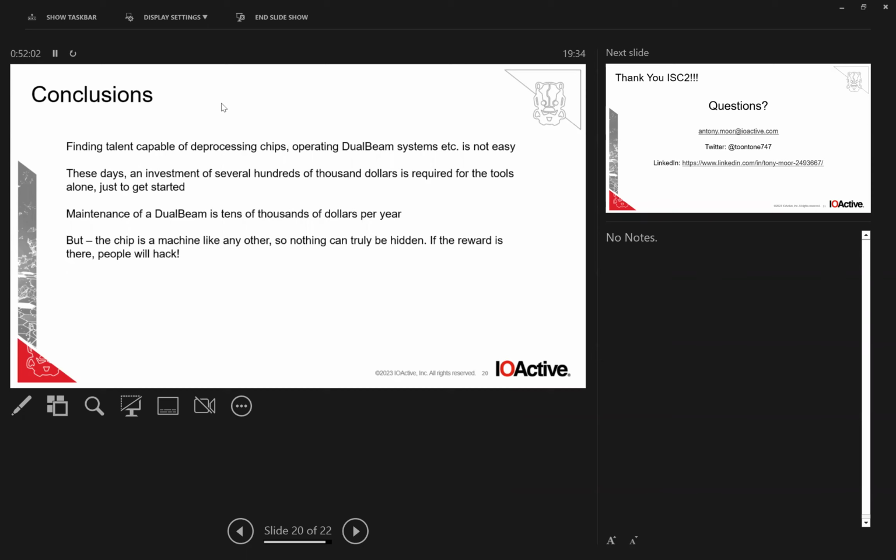John? Yeah, so a good way to think about the net list is it is an abstract, high-level representation of what is burned into the silicon during the lithography process. So it's something that you can look at and analyze from a logical standpoint. And if you think about traditional reverse engineering, this is a kind of intermediate stage when the software, where you're looking at the control flow and how things interrelate and the overall software architecture. So it's very similar to that. So this is very common. I like VHDL, Verilog. Those are common terms we hear talking about specific implementations of a net list.